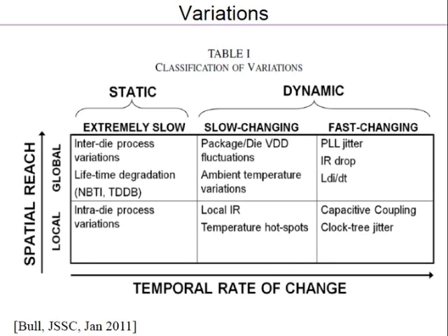That is called inter-die variation. Die means a chip, so across chips there is a variation for the same transistor. Now within the same chip you have many transistors. Same AND gate you are using multiple times. Even though you have used the same AND gate, you have just taken a copy of it and put it elsewhere, the threshold voltages could still be a little different.